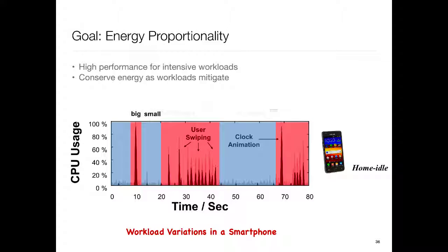It could either be the operating system, or could even be some sort of a state machine sitting on the chip in hardware, which is just monitoring how busy the processors are, and then just switches back and forth. So this is a form of multiprocessing, multiple cores, except it is heterogeneous multiple cores. Normally, when Intel says a processor has 4 cores, what they really have is 4 identical cores. So that's homogeneous multi-core. This is heterogeneous multi-core. And why stop at 2? You can have more of them.